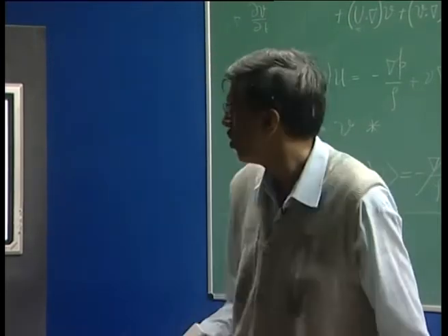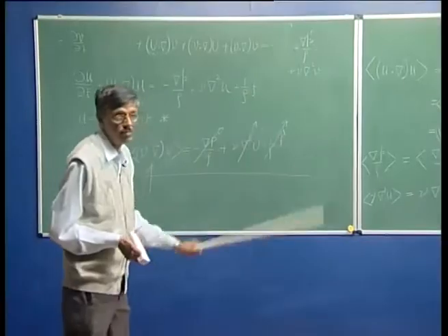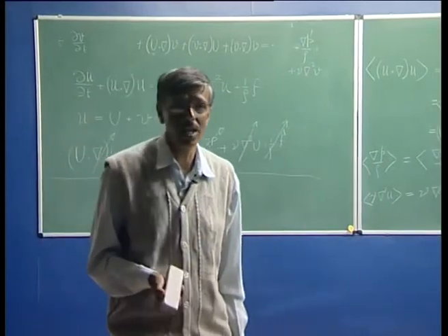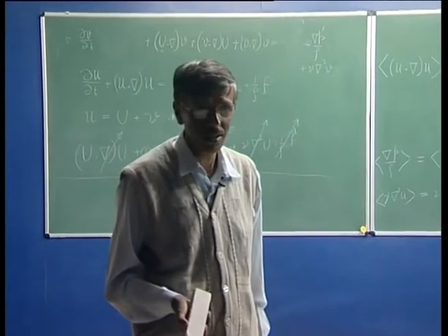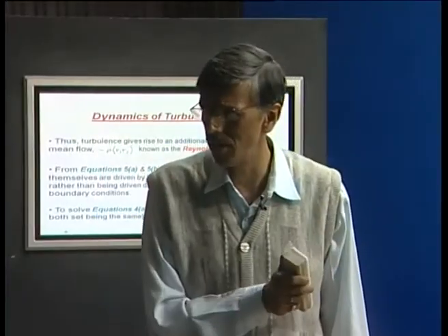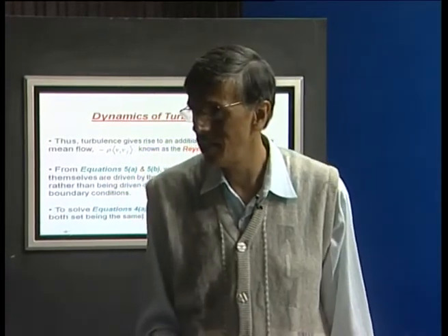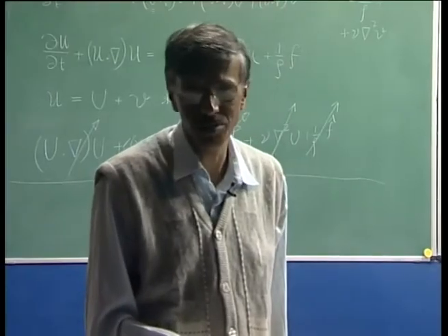So, the boundary condition really does not drive the fluctuation. So, please do understand, this is very, very crucial: in a turbulent flow, what we see as a fluctuation is driven by the mean flow itself, and also of course, the applied pressure gradient. Body force per se does not give rise to turbulence.